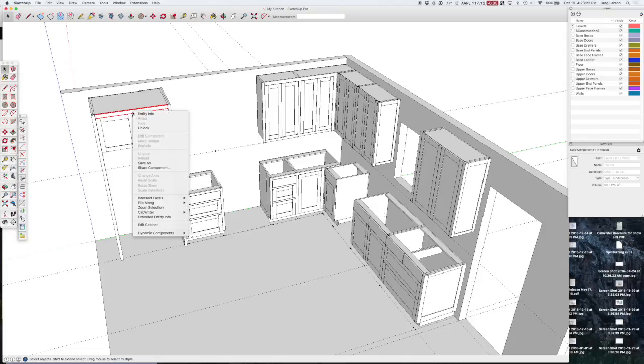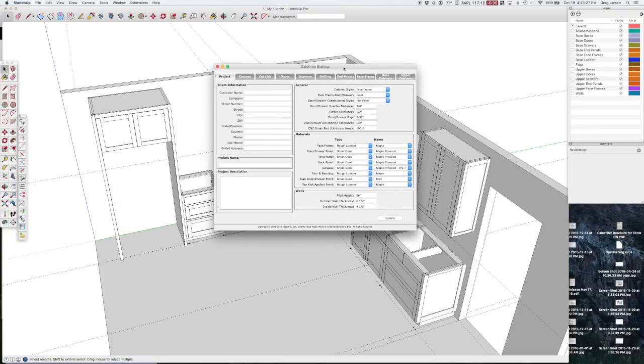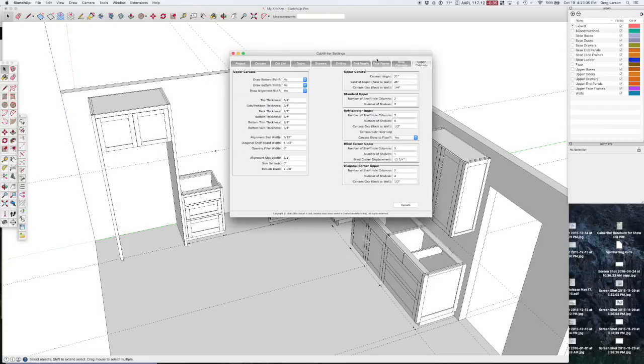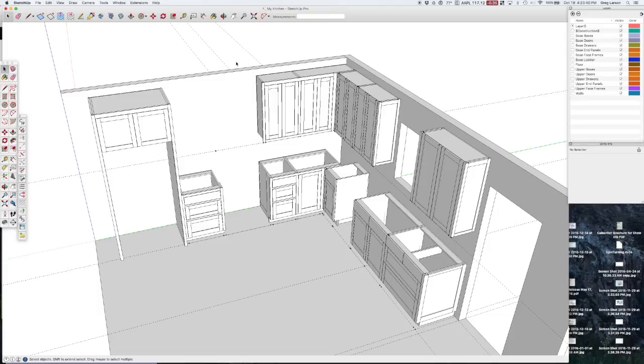If I want to go over to this refrigerator cabinet and work on that, I can load that up, and you'll notice that now I've got a cabinet height up here of 21 inches, the cabinet depth of 26 inches, and so on. So if I wanted to go draw another refrigerator cabinet, I could do that, or I could pull that into another file, pull the parameters out, and use that. So very powerful. So we're calling it like cabinet DNA. The DNA always follows the cabinet around, so that you don't have to remember exactly what you did when you built that cabinet.